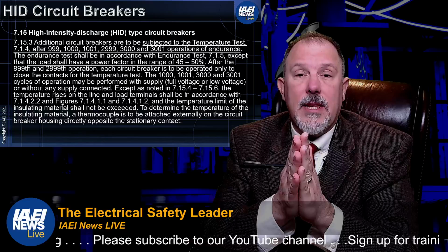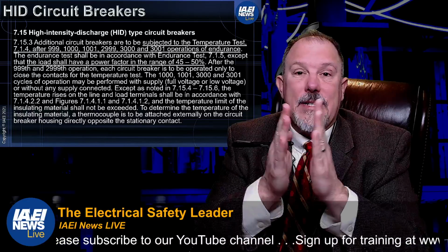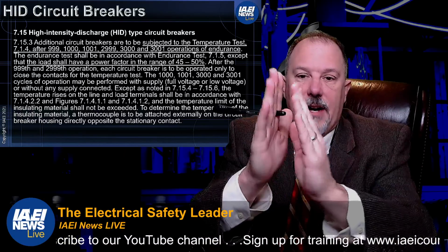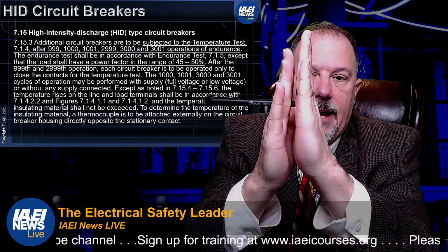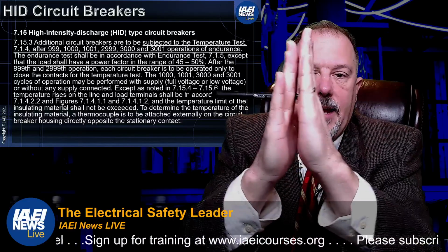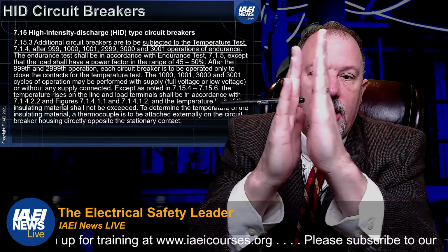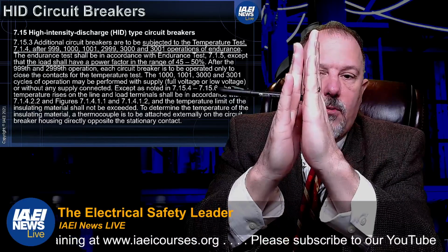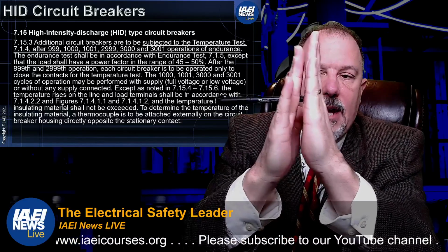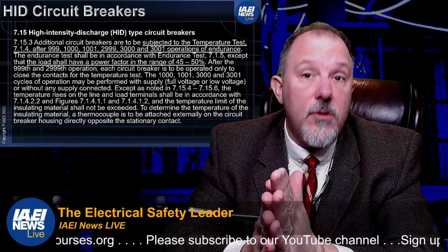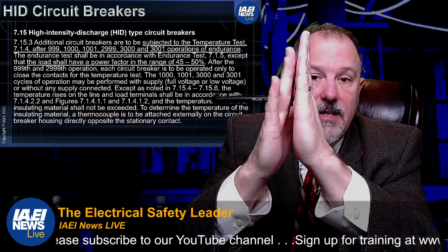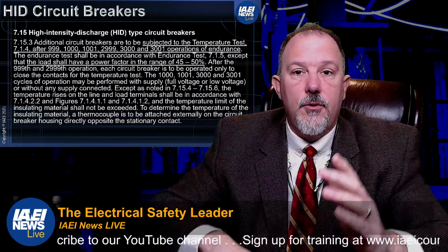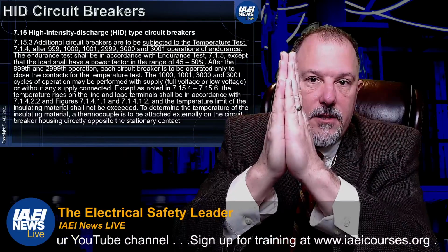You don't want what they call dimpling. What dimpling is, if I, for example, had a dimple on my circuit breaker contact, and instead of closing and creating a contact along the entire surface, I'm only connecting on that dimple or multiple dimples. All my current is flowing through one point and not through the entire surface.